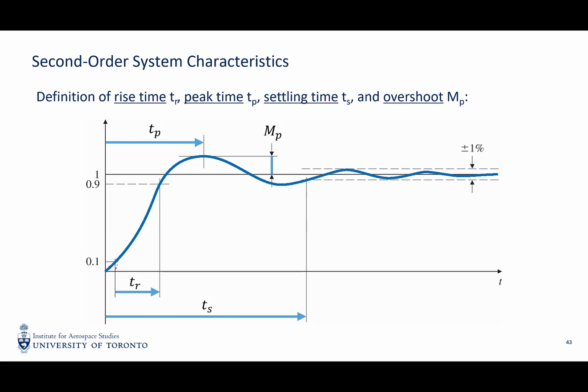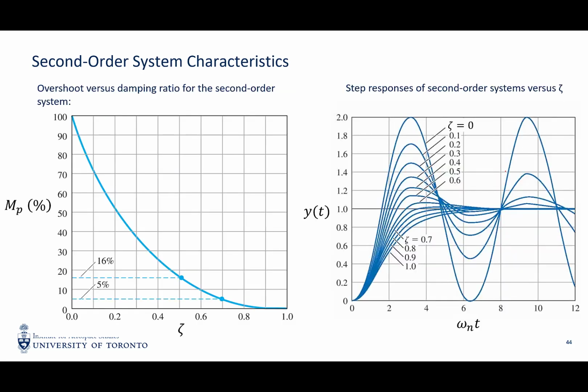The rise time is from 0.1 to 0.9. Settling time is when the trajectory afterwards stays within 1% of the error band. And here are some different responses if you pick different zeta and omega. So in terms of achieving desired performance for a simplified system using PID, you can just use zeta and omega to determine the feedback gains Kp and Kv. Good.